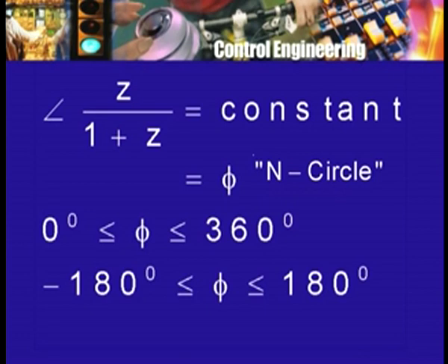There is a contour map for the gain, and there is a different contour map for the phase shift. And then in exactly the same way, as you move along the polar plot, that is, as you trace the polar plot as a function of frequency, what is the G j omega at each point, the intersection with the N circle will give you the phase shift at that point. So, this is the set of M circles and N circles.